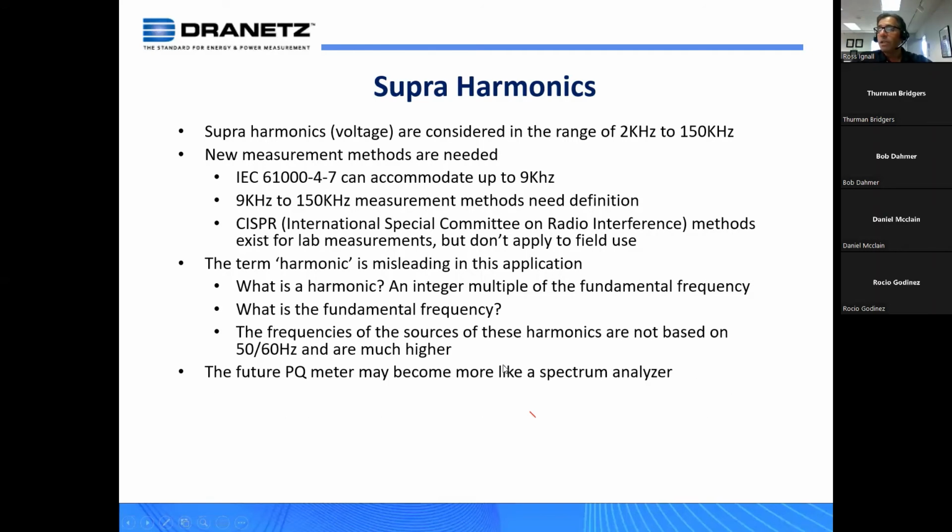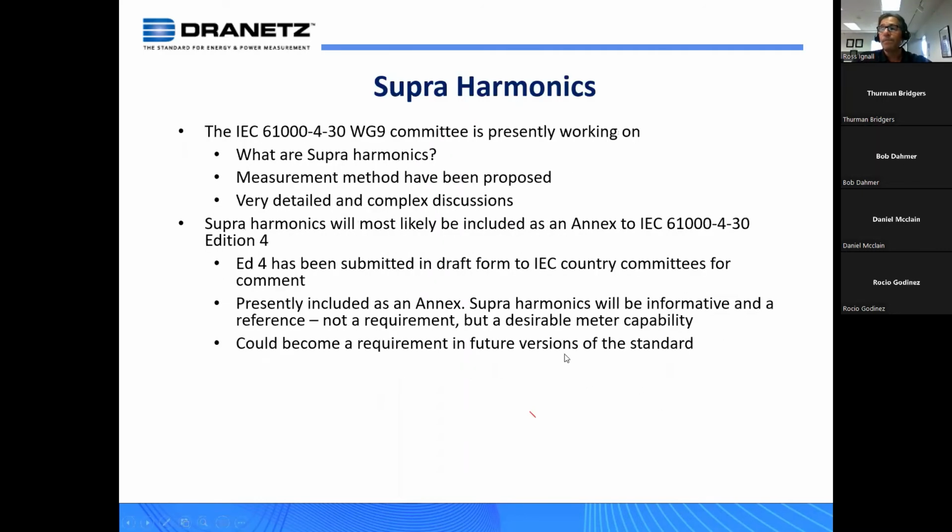So really, in a nutshell, the future PQ meter may become more like a spectrum analyzer than a PQ meter when it talks specifically about superharmonics. It's just looking for frequency content, not based upon any particular fundamental. So that's kind of where this is heading for the time being.